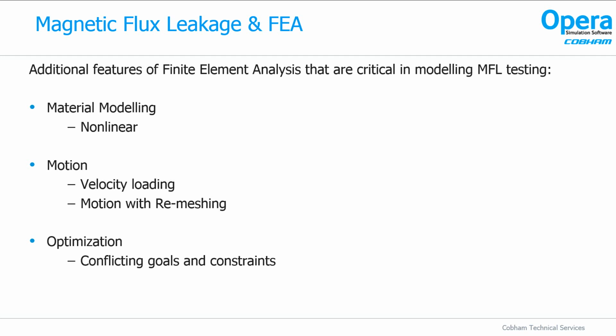MFL simulated with purely a velocity effect gives rise to an additional difficulty in both signal interpretation and modelling due to the formation of eddy currents when an excitation source moves over or inside a metallic pipeline. Numerical approaches to this problem include 2 schemes. Firstly, it can be solved quasi-statically with an extra movement component added to the formulation, or secondly, the relative movement of the probe and the pipe can be analysed over several time steps, with the problem automatically repositioning and remeshing as the solution progresses.